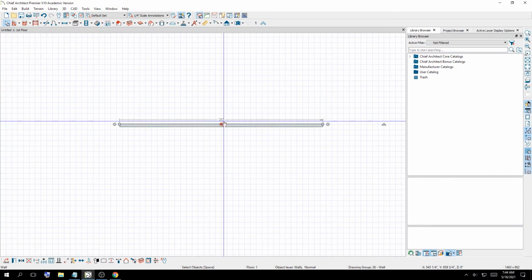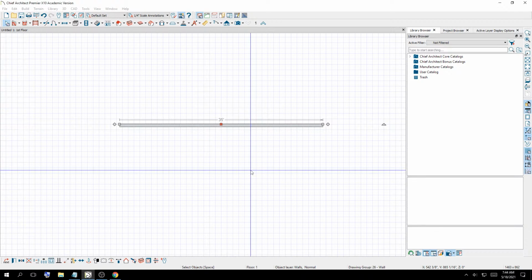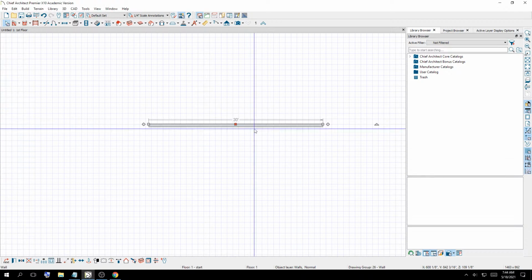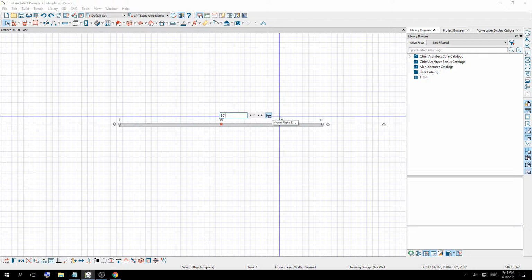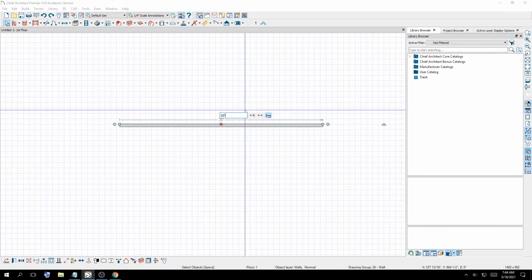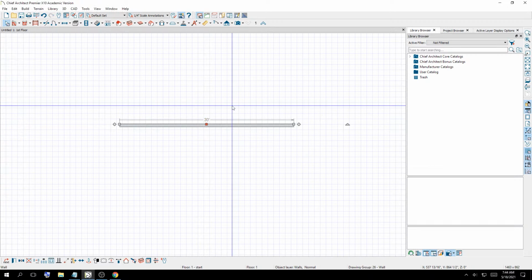So I'm just going to change it back to 30 feet, apostrophe, and I'm just going to pull it in from the same edge it came from and press enter. And actually I did the opposite. So let's just go back. I'm going to hit Control Z and do that again. 30. And the arrowhead is going to be the direction of what will change. So as you can see, the arrow is pointing to this side of the wall. So when I press enter, this side of the wall should be the one that moves. As you can see, that's what happened.